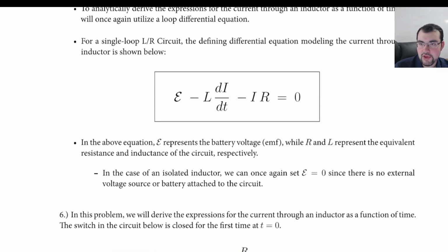So we'll do the same thing where we add the battery and subtract off everything else. We don't mess with any signs, no funniness there. We just say the battery supplies an increase in potential, and then you drop across everything else. And if there's no battery, you still write it like this, and then you just cross it off. I call this the phantom battery technique to getting all your signs right.